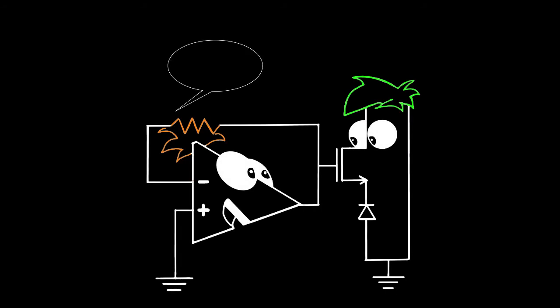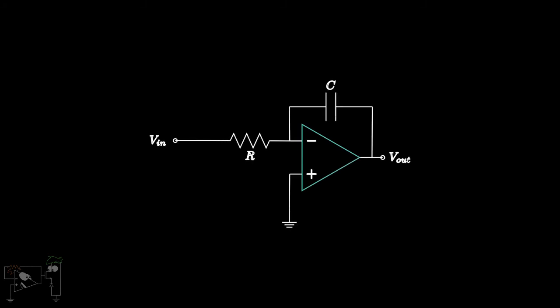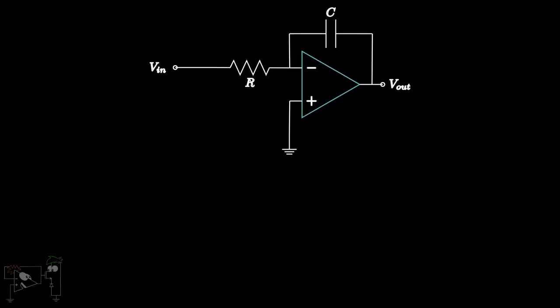Why do we need op-amps to build integrators anyways? Can't we just use passive RC circuits instead? The answer lies in the virtual ground condition of the op-amp. The ideal integration shown before occurs because the left plate of C is pinned at zero potential. To gain more insight, let us compare the integrator with a first-order RC filter in terms of their step response.